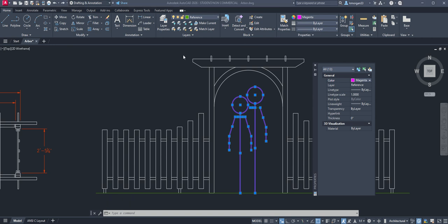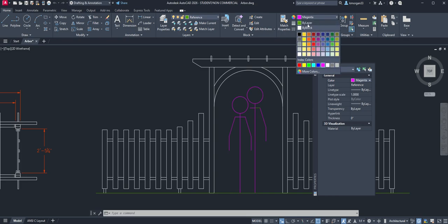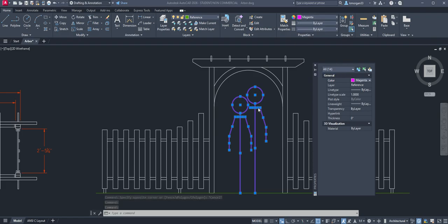Of course, the overwritten color usually shows up in the properties. So when you look at the Home tab and you go all the way down to properties, look at this, where the magenta color shows up. Of course, you can go back to the color before, so this is going with the layer. If you go with the layer, it will definitely give you the green color, like that. Of course, I forgot to click one of the little tiny lines, so I just overrode that.